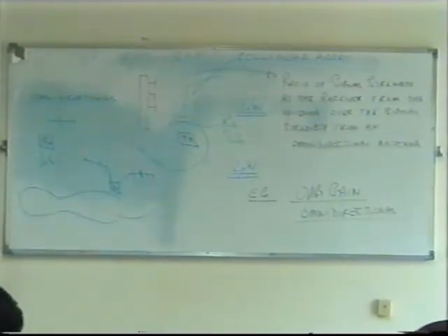That's basically it. You get nothing for nothing. You're just using the signal strength, the power, in a different way. If you like, at 0 dB you transmit 100; if you decrease to 50, we can use an antenna with 3 dB. What we're saying is that would give you the same signal strength at the receiver if you use 50 watts with a 3 dB antenna, yes.